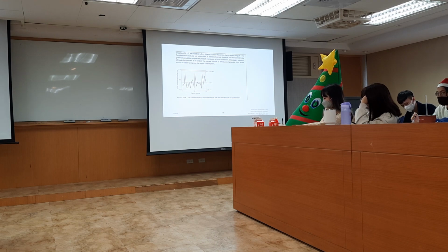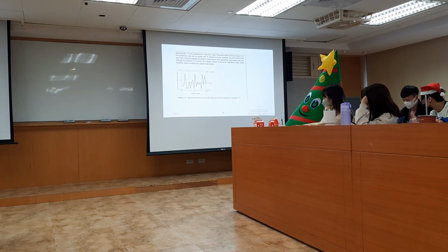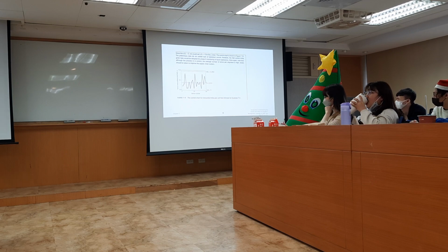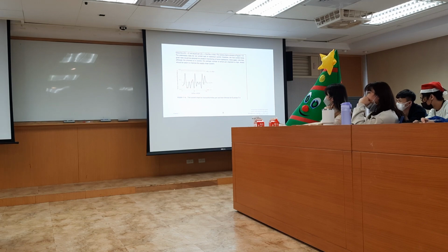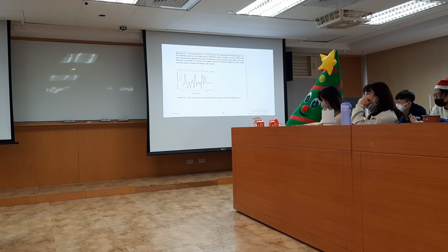The control chart is shown in this figure. Most of the points in the preliminary data do not exhibit any lack of statistical control, so all the points are quite random and do not show any particular pattern. All the points fall within the upper control limit and above the lower control limit, which we set back to 0. Once again, note that although the process is in control, the average number of errors per shipment is still high. So action must be taken in order to improve the supply chain system.